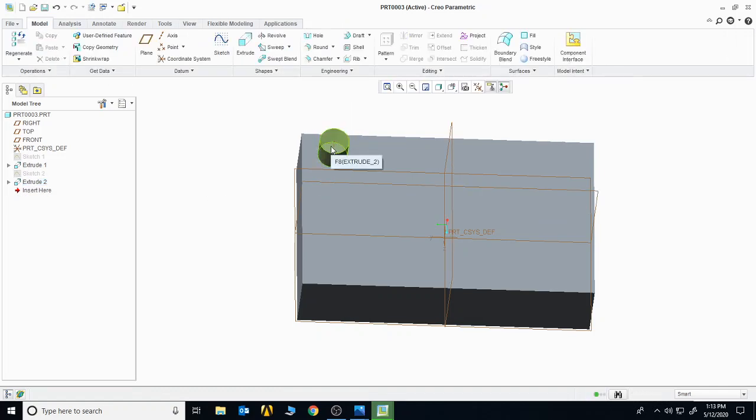I want this cylinder to be placed at different points along this particular surface that I have drawn. So there are a number of options for that. You can either keep on going into the sketching plane and keep on sketching the same circles and getting them extruded over and over. Else you can use the pattern command for that. So you can get a number of cylinders in whichever direction you want, or in whichever dimensions you want, or along different points that you want. So we will be using the pattern command for that.